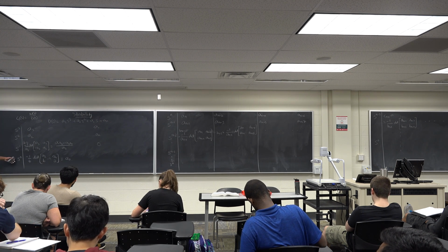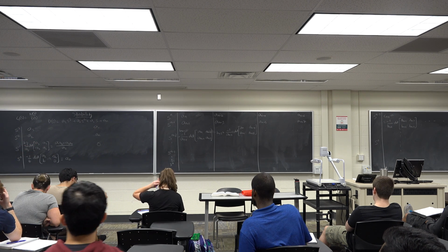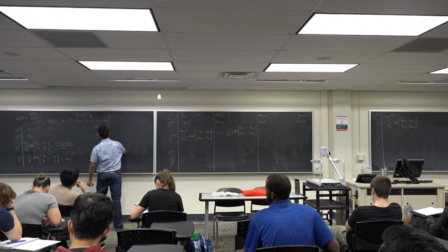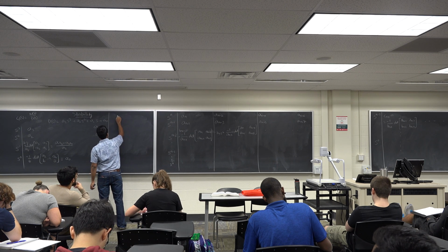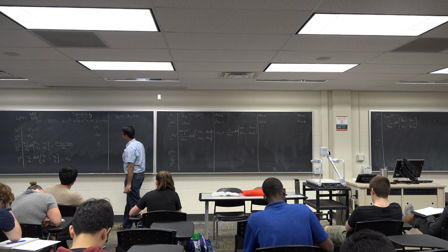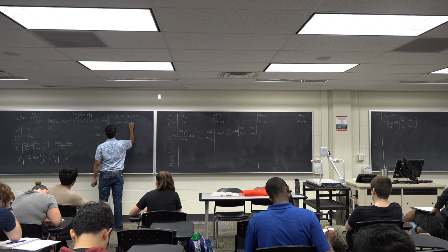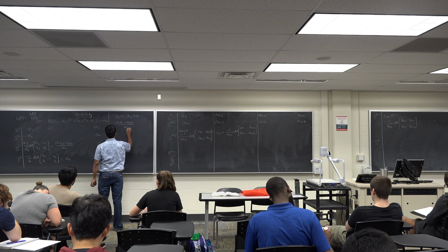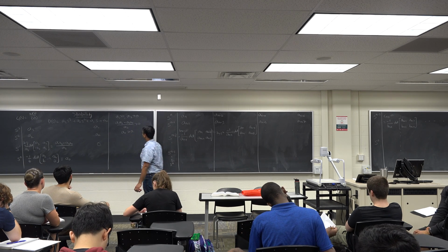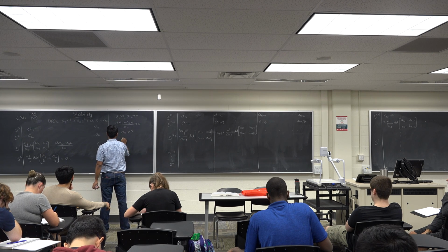Okay, is the derivation clear? Just follow the Routh table that I've written down there. And so what do I get from here? When is a system stable? So let's say A3 greater than 0, A2 greater than 0, (A1 A2 minus A3 A0) over A2 greater than 0, and A0 greater than 0. If all these conditions are satisfied, then it means the system is stable.